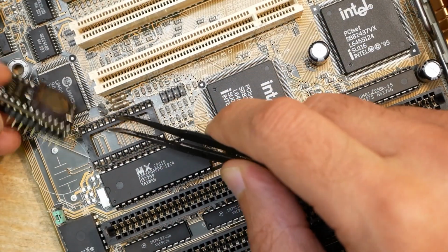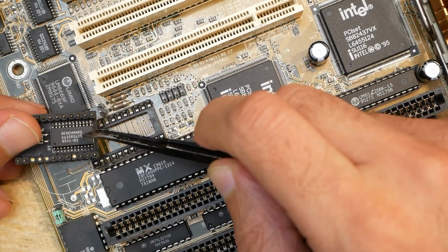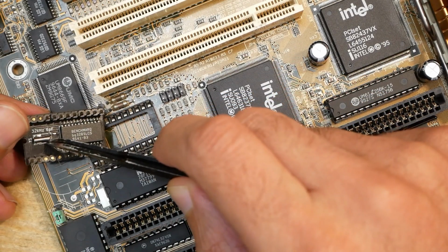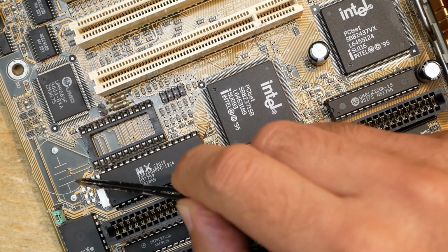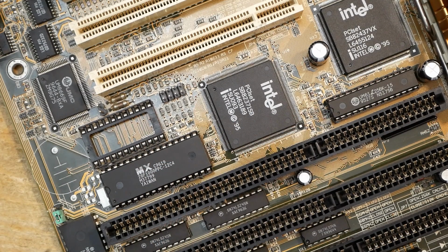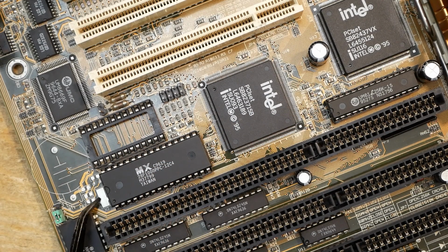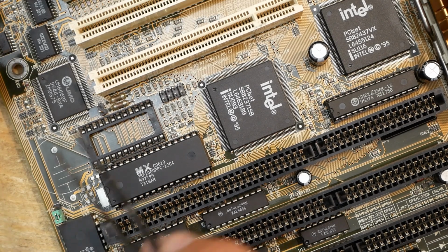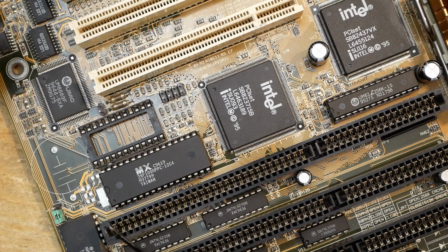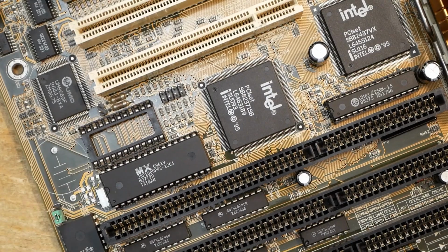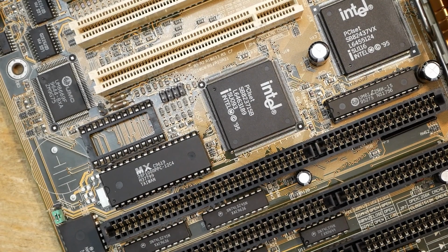As I mentioned before, in such a module not only a battery is included, but also the RTC chip as well as the 32 kHz crystal oscillator. Now, if we look at this board, we will not only find the placeholder for the battery, but nearby also some unpopulated components, one of which is a solder pad for a crystal oscillator. And if we follow the traces from those pads, we will see that they, as well as the battery poles, are all connected to the socket for the RTC module. So on this board there is no need to use a complete RTC module, but we could solder the battery and the crystal oscillator into the mainboard and insert the right RTC chip into that socket.